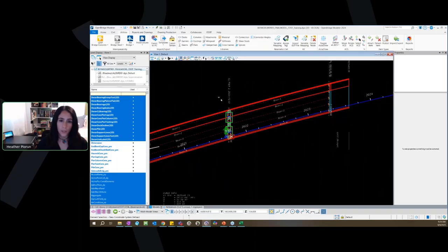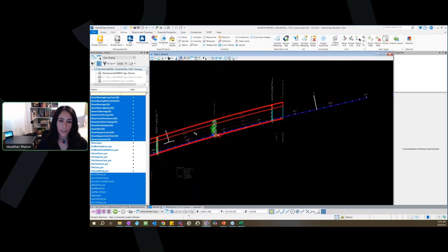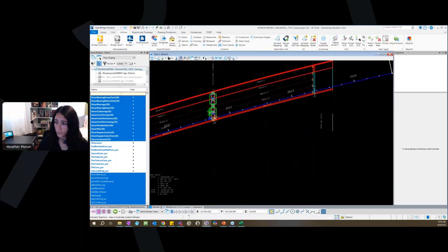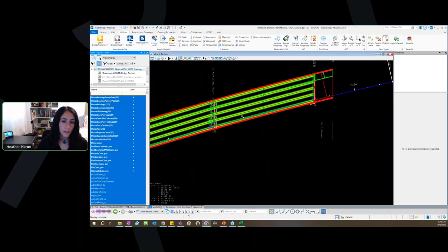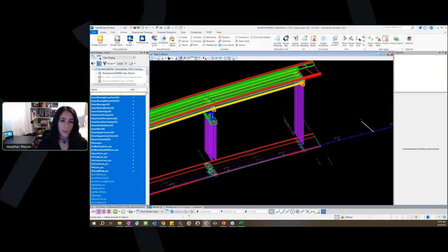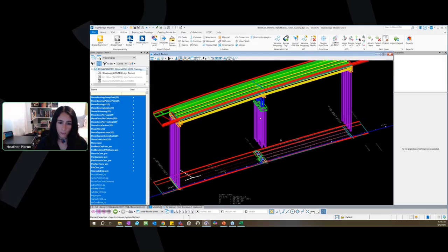So you can always go through and you can redefine this, or you can reset your ACS so it'll go back to basically north being oriented for your unrotated view. Okay, so I went through that. One more thing that I'll mention, so I'll turn back on all the 3D elements, just how to rotate around within the view here.